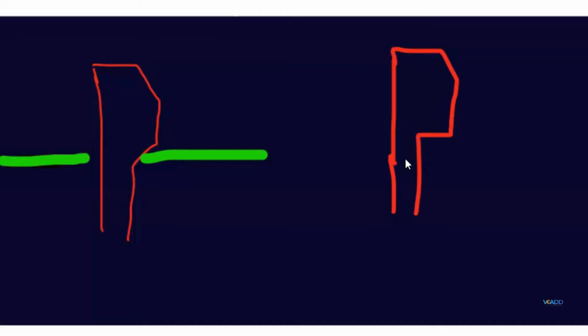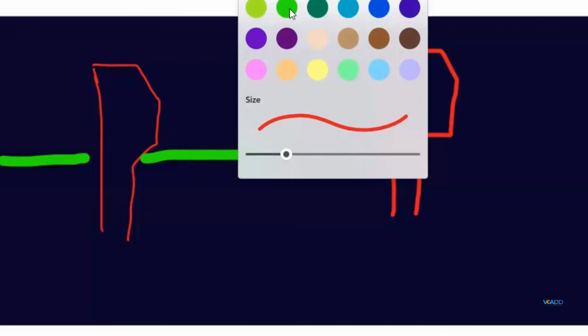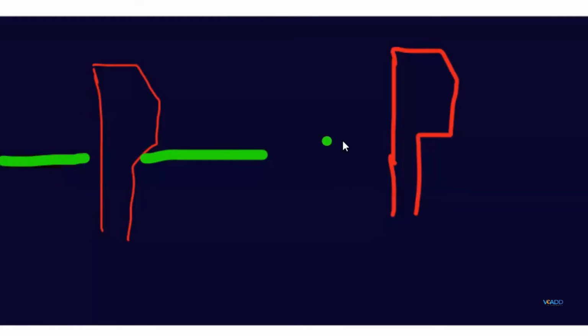The bottom of the snap is exactly straight. That means what will happen here? Suppose this is your mating part. Now just imagine logically, guys, if you pull this part down and the bottom of this snap is flat, is it really feasible that the part can be disassembled?